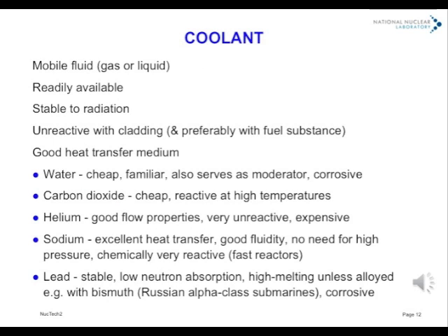The coolant must be a mobile fluid, whether liquid or gas, readily available, stable to heat and radiation, unreactive with the fuel cladding, and in case of damage with the active substance itself, and a good heat transfer medium.